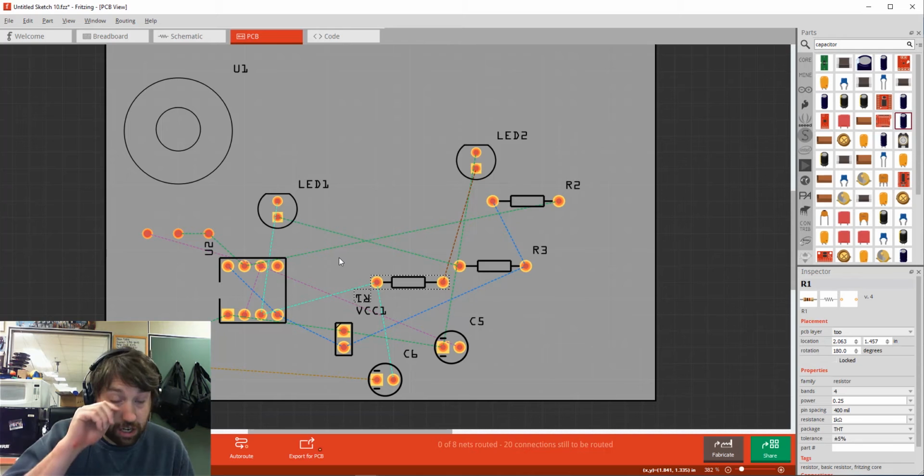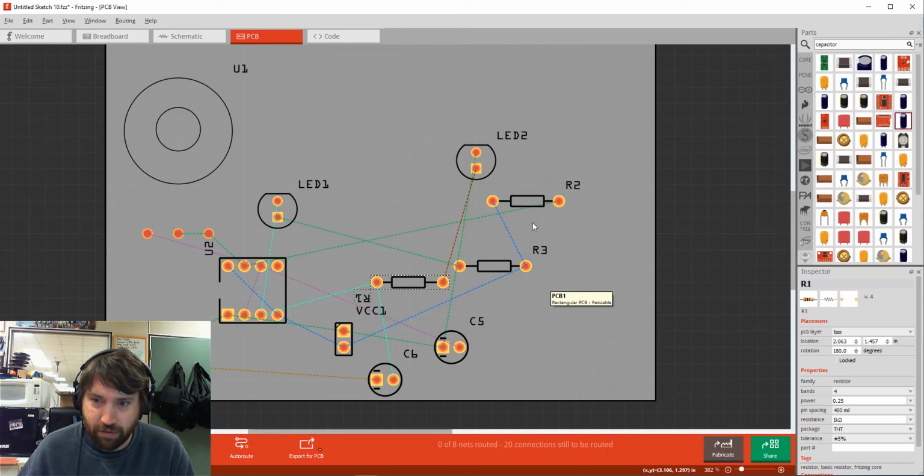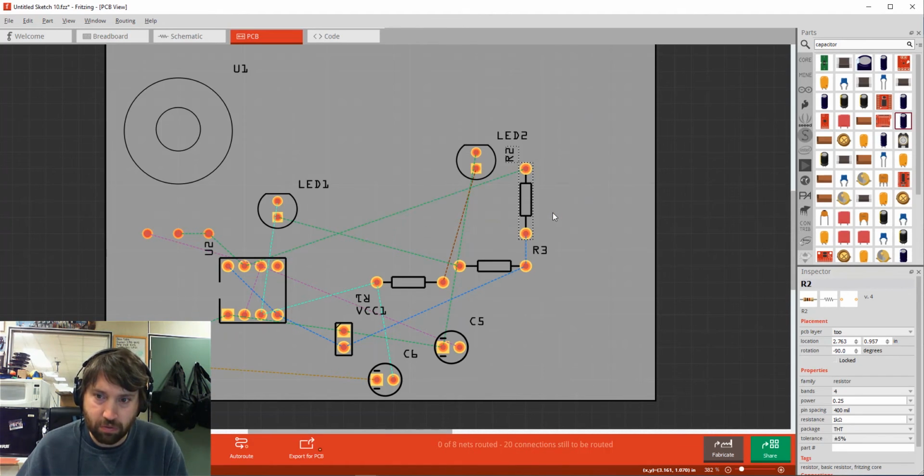Since this is a single-sided printed circuit board we're trying to make, our one constraint is that we can't have any overlapping lines. Now, it sure looks like I've got a lot of overlapping air wires right now, and I do. And that's where we have to start untangling things. Certainly, anytime we have a component, like this resistor would be a perfect example, that its leads are crossing with itself, I can uncross them just by rotating the object. Right? If I rotate it, it's going to unwind those 2 components.